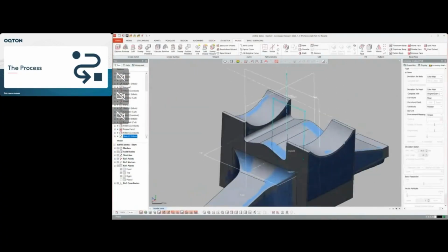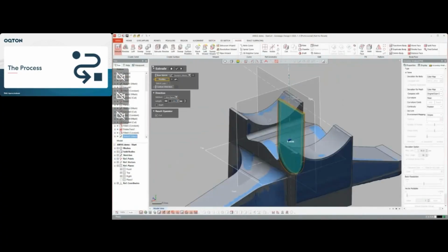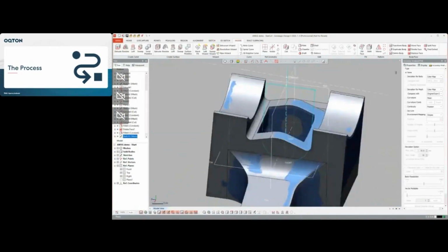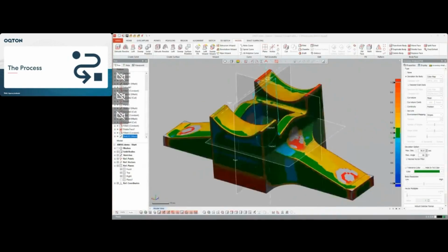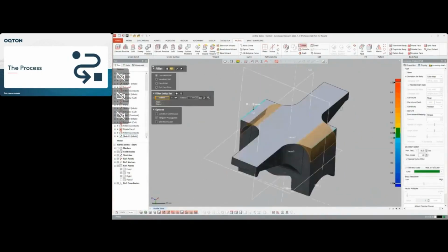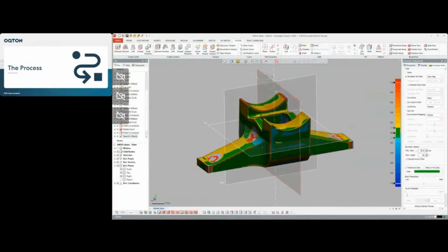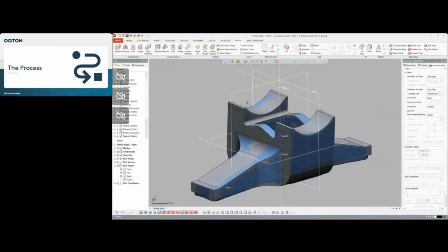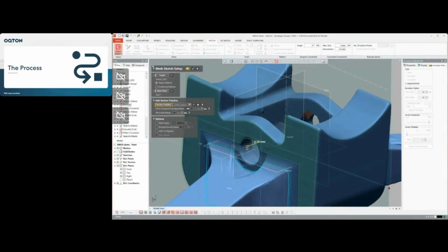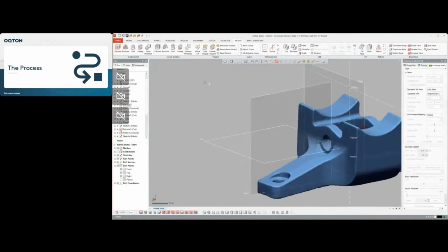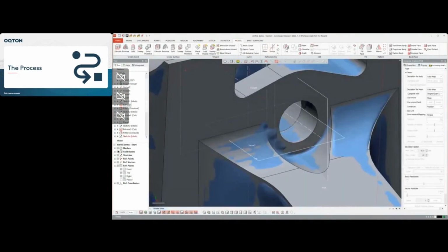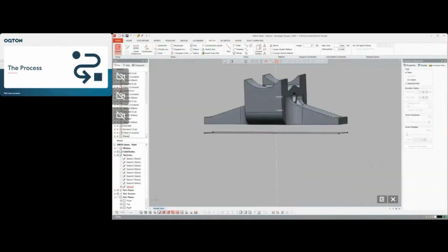Then I use a 3D comparison tool to show how closely we're matching that. We're extracting different features over and over, and intermittently I go to the accuracy analyzer and compare the results of what I'm modeling with the original scan data to make sure I'm modeling something that is accurate to what's there.